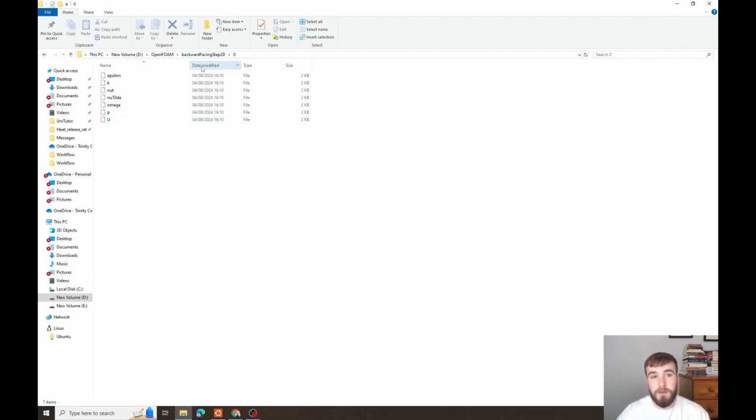So I'll explain these a little bit later after I show you what actual test case we're running here. In the constant folder, this is where you define your models, mainly if you have any chemistry, combustion models, thermodynamic models. And here we've got transport and turbulence are the models that we're using. And finally, system: this is mainly different files you use for meshing, for your finite volume solution, and sometimes some post-processing functions go in here. So there are the three kind of file directories.